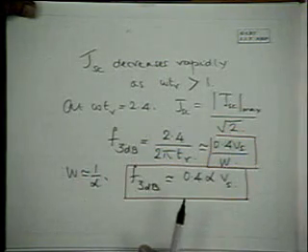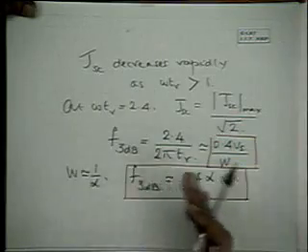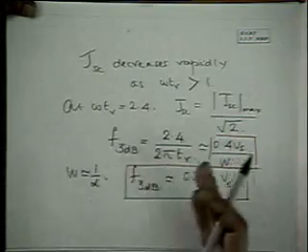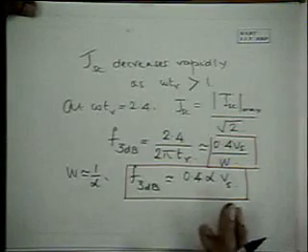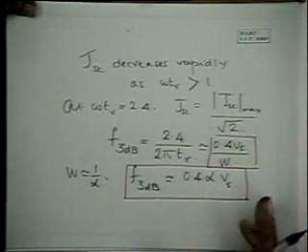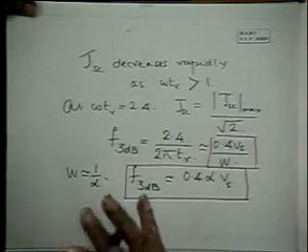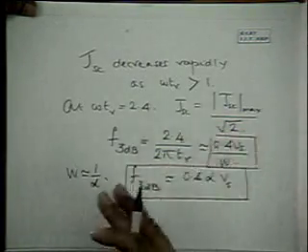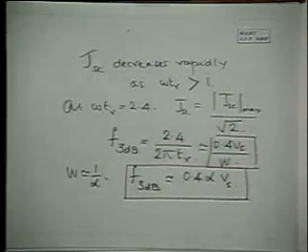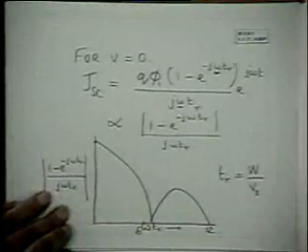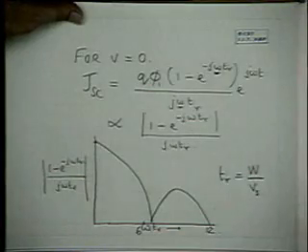Why is that? Because after all, the carriers take a certain time. When you have a modulated signal, the carriers take a certain time to move through the I layer, and as the frequency becomes very large, then the carriers are out of phase. When the signal is the maximum, the carriers become out of phase. So in this same graph, we can plot the phase shift.